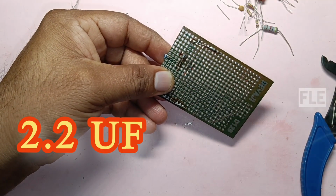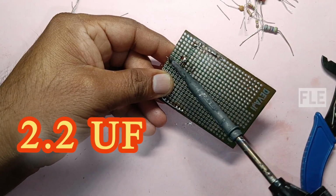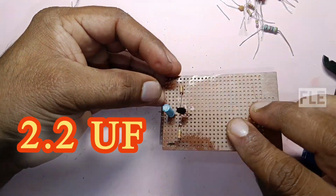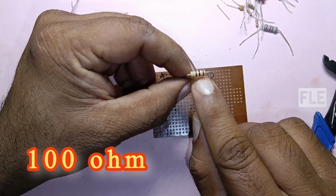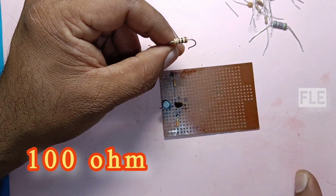While placing components on the PCB, refer to the circuit diagram. The 2.2 microfarad negative terminal is connected to the base and the other terminal is connected to the 100 ohm resistor.